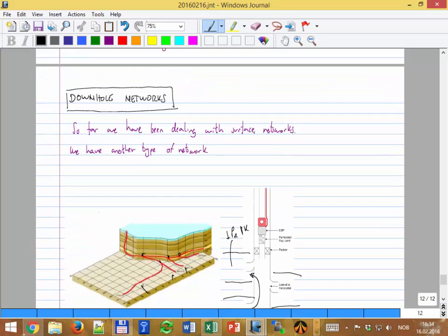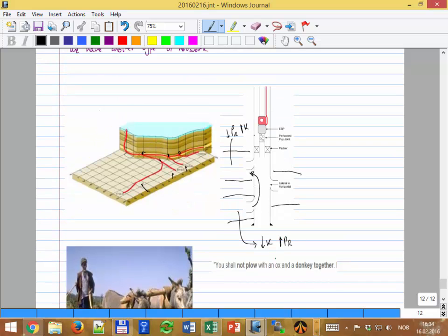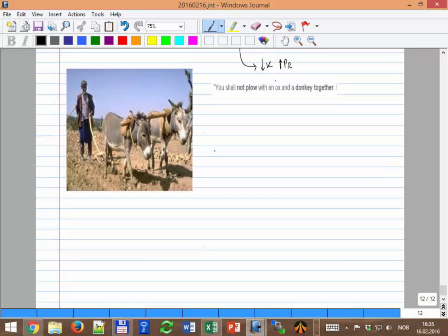In pipes, it's slightly simpler because in the wells we have a check valve, something that impedes the rate from going in the opposite direction, actually going into the well. But when we have these systems downhole, it might happen that you don't have anything that blocks or dictates the flow direction, okay? So that's a limitation that we have to live with. So that's the right way of doing it.